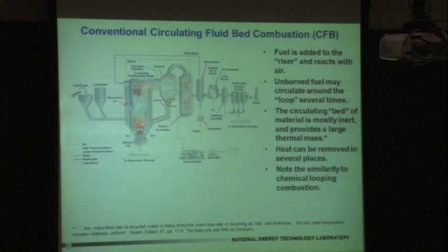Well, in a conventional circulating fluid bed combustor, an example of one here, I showed this before in a more schematic way, but the fuel is injected at the bottom. It's carried up. There's heat being extracted by the walls of the device here. You separate out some of the char, and there's sand in there that you're using to moderate the temperatures. Then there's a heat exchanger right in this portion of the leg that takes heat out of the solids right at that point. Then you keep re-injecting any unburned carbon, as well as the bed material itself, which is ash and sand. And then you actually take some of the heat out from this convection section down here before going out the back end of the thing.